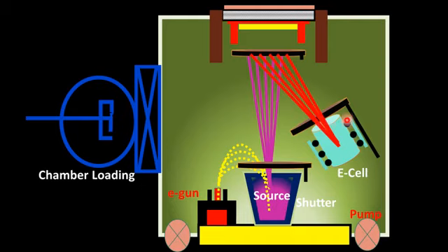Student, please note that the effusion cell is based on inductive systems. It is based on induction coils, and the induction coils thermally evaporate the dopant which is present inside the effusion cell. After the thermal induction, the dopant is evaporated and transported onto the surface of the substrate.